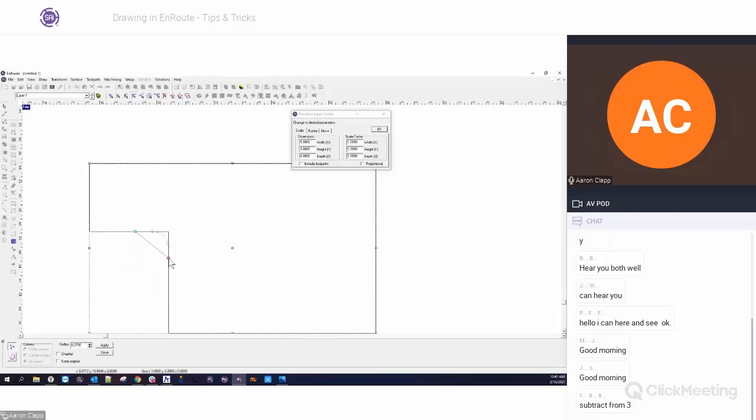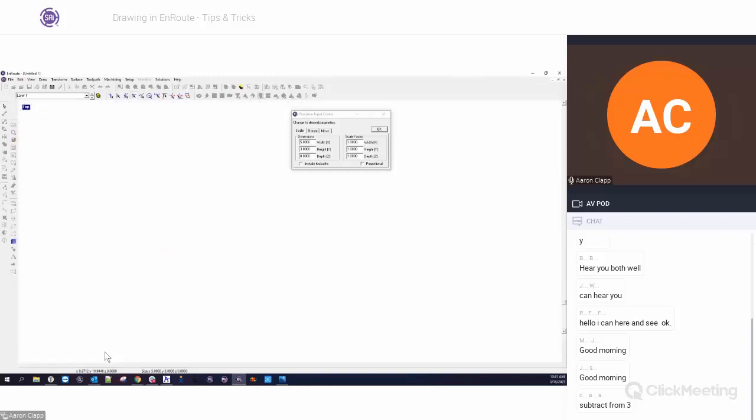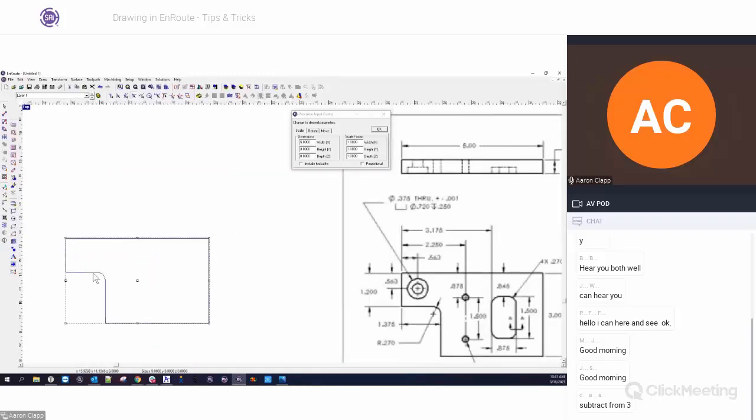They can be all the way up here. Anyway, this just defines the boundary in which the radius is going to look for a corner inside of this area for me to do. So radius 0.27, hit apply, just like that. Now we've got our radius.